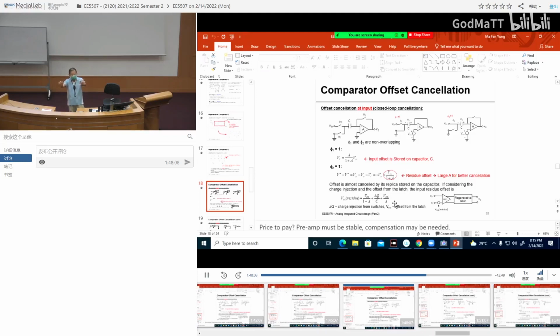It's exactly the same in the schematic, but when you want to simulate a mismatch, you know that they are slightly unbalanced. So the simulator, when you run the Monte Carlo, would change some parameters to model this imbalance. And then you can see the offset. You know where Monte Carlo comes from, right? Gambling, Monte Carlo. Statistical.